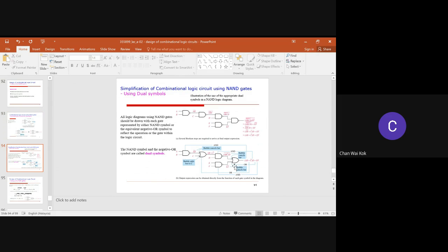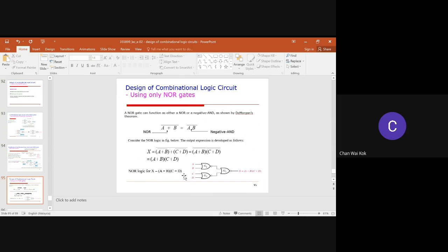Okay, the next example, you have a circuit like this. So you change this to a not-OR gate. Then this is a bubble, isn't it? Then these two bubbles will cancel off each other. Then over here, you have a bubble. This one will cancel off each other, and you add another NAND gate to it. Then it becomes an inverter.